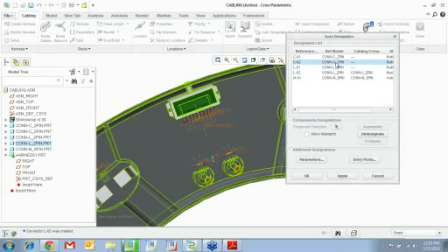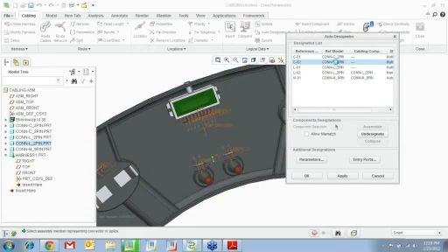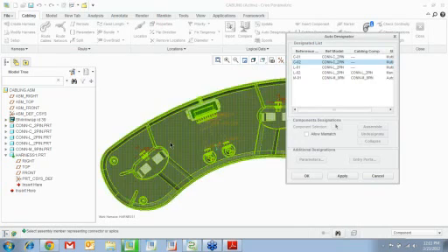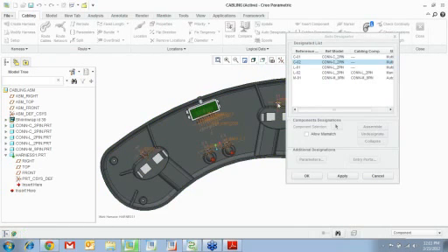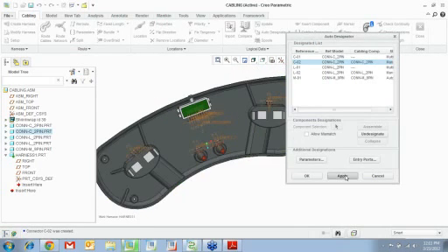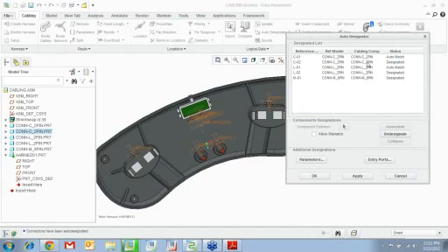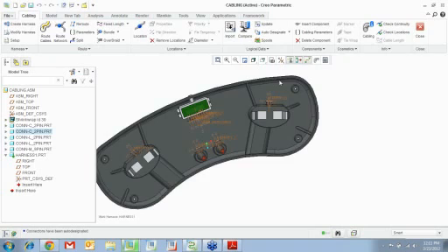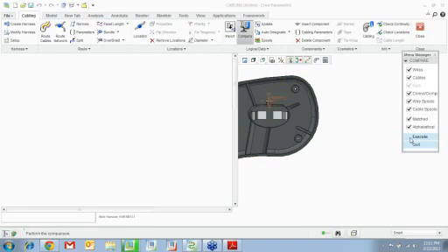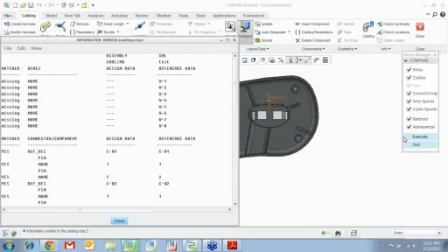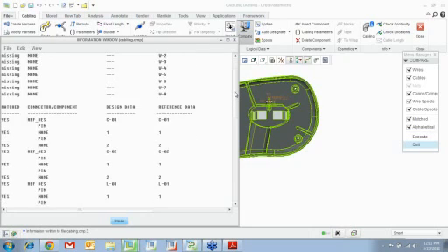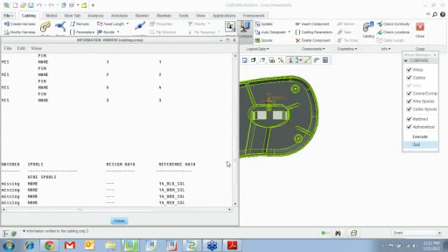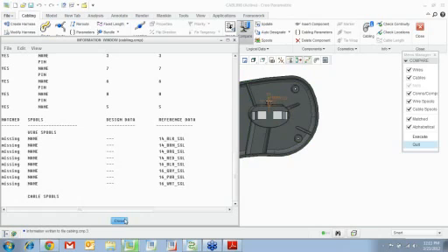Right? I picked one. You see there are 2 of them, 1 and 2. So I say this one's number 2. See that? And then you hit apply. You see it auto matches the other components. Now you say okay, you can go update it and do a comparison real quick just to see that. Notice the wires are not there, but everything else has been matched. Okay.